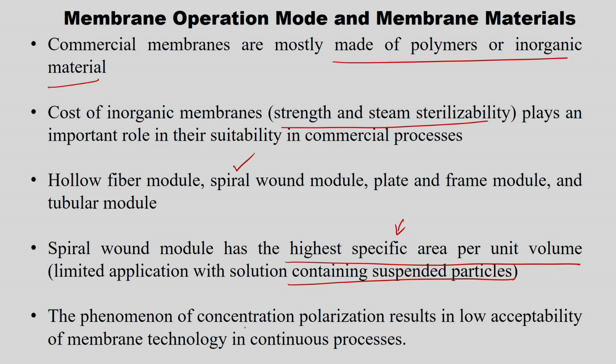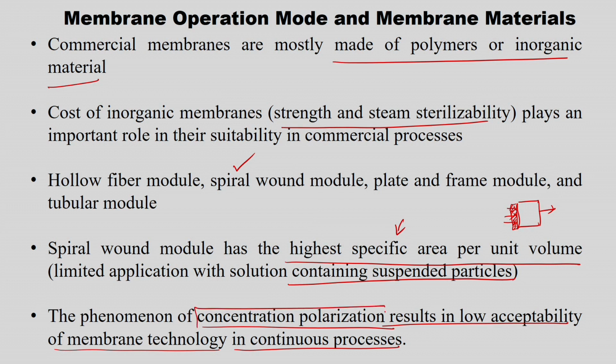The phenomenon of concentration polarization results in low acceptability of membrane technology in continuous process. This concentration polarization is nothing but, so I have a membrane, and here the solute gets retained and the permeate moves out of the membrane. So, after a certain time, this retentate gets concentrated, so it forms another resistance for further flow of the feed through the membrane. So, that is nothing but concentration polarization.